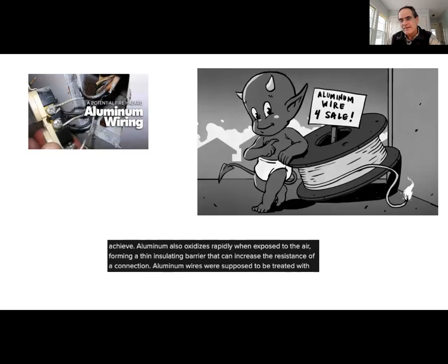And as it gets thicker, the resistance of electrical connections between aluminum wires starts to grow. When we pass a large current through that, there's joule heating, and eventually the joule heating might be enough to ignite the flammable aluminum wire. So, lesson learned, I guess, but an interesting application of tunneling.